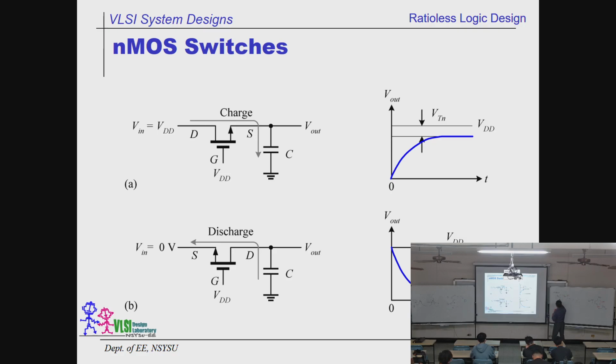When one wants to pass high, to deliver a signal, VDD equal to high. You want to pass high? Yeah, you got high, but you got VDD minus VTH. You got the weak one. Yes, you still pass 1, pass high, but this high is lower than what you expect.